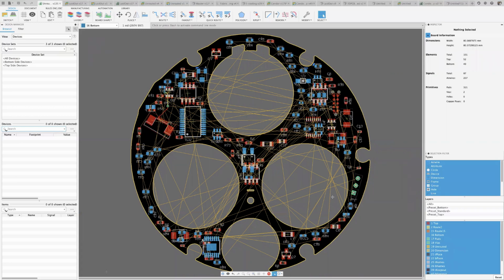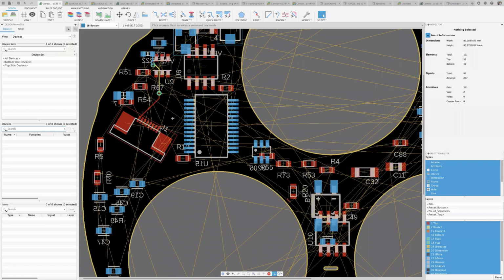So this is what the circuit board looks like. It's been laid out. I do have some traces already here. So as you could see, manual routing in Fusion 360 has a host of capabilities. So we have our route command. So we have our route manual, differential pair, route, and meandering. So you could do length matching, and you could do length matching for differential pairs as well. Now, I could do fan out. So I could fan out all my, let's say, my ground signals over to a polygon, which could be in the internal layer. I have the quick route as well.